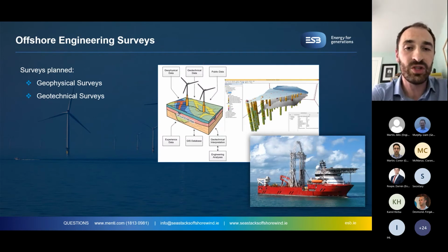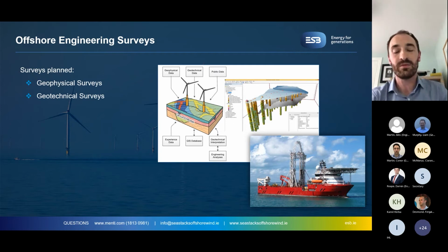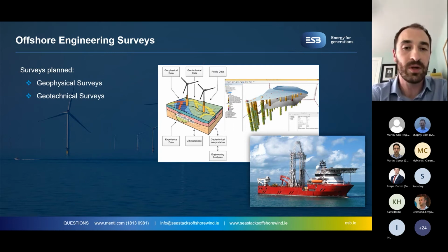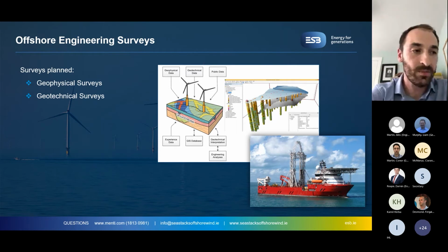Following the geophysical surveys, geotechnical surveys will be undertaken. And again, a typical vessel that you might see in the offshore environments during this phase is shown on the bottom right. Information collected as part of this will be combined with the geophysical survey data to create a project ground model. And one of the key objectives with collecting intrusive data is to understand the engineering characteristics of the seabed conditions, which will inform foundation design and offshore cable installation methodologies.